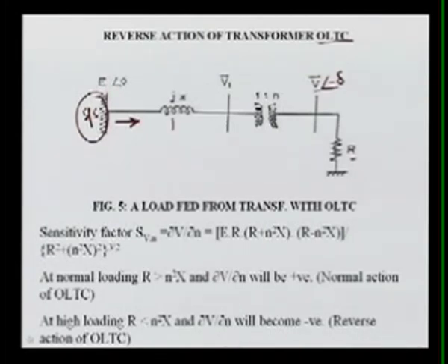Here we have a line, and this is your transformer, and this transformer has a turn ratio of 1:n, meaning V1 over V will be 1/n, this voltage divided by this is N1 upon N2, so we are getting this ratio. So now this V will be nV1.